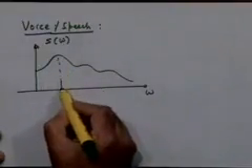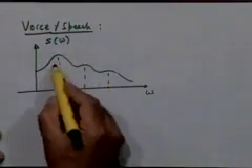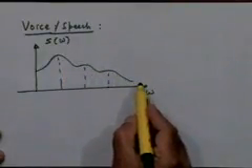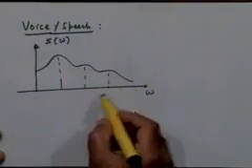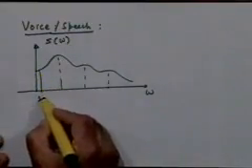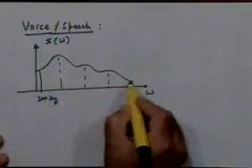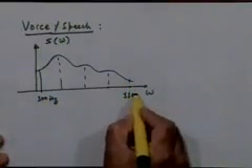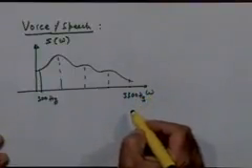There will be a few major peaks in the spectrum, but on the whole, the spectrum will start decaying after a few hundred hertz. For telephonic communication, it is found that if you concentrate on the energy between 300 hertz and about 3300 hertz, you capture most of the intelligence as well as the essence of speech, without losing much on either the intelligence or the quality of speech.